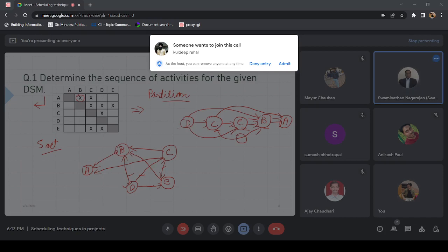If C is giving parameter P1 to E, and it is also generating P2 as output, which is required for working on B. So this gives you a sense that there is some kind of information flow, parameters flowing from one point to other. In this case, activities and parameters. If you were supposed to make a CPM network or find the duration of these activities, it would have been quite easier, right? You have a start point, you have a finish point. These are in series. You just add the duration and find out.